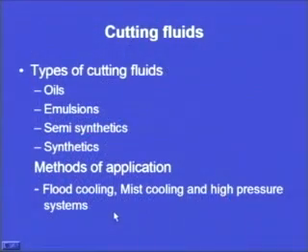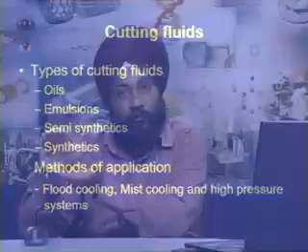Now, what will be the requirement? The requirement will be in terms of either we want only cooling, or we want only lubrication, or a combination of these. Now, how can these be applied? These can be applied by flood cooling, in which we directly flood the cutting zone, as is the case with the floods or flash floods that we see during the rainy season. The cutting fluid will be flooded in a large quantity at the cutting zone.